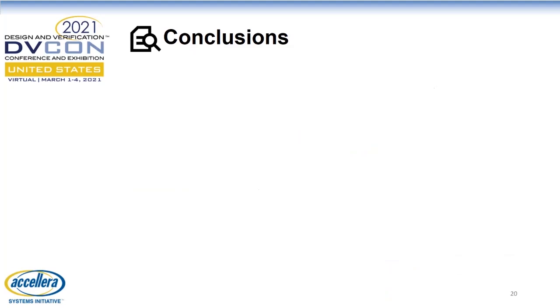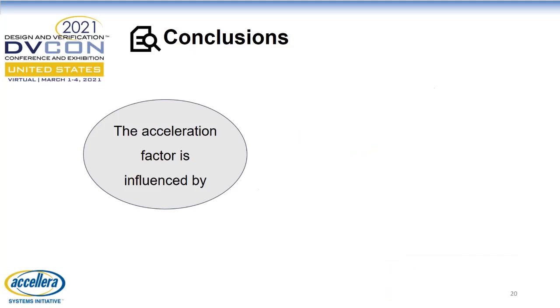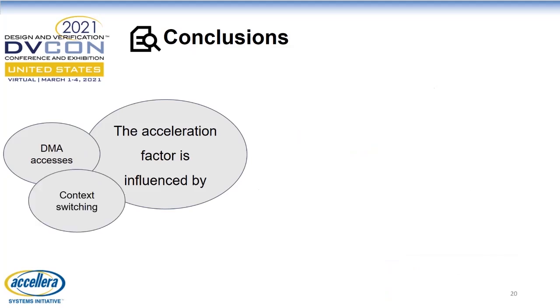This brings me to the end of the presentation. To summarize the key points, when using OFC, there are several factors that you should consider in order to achieve a greater acceleration factor. Firstly, the number of DMA accesses should be limited to the minimum necessary if you want to achieve a better performance. Then, as we saw in the results presented, having less context switches between send and receive operations can also lead to an increase of performance.